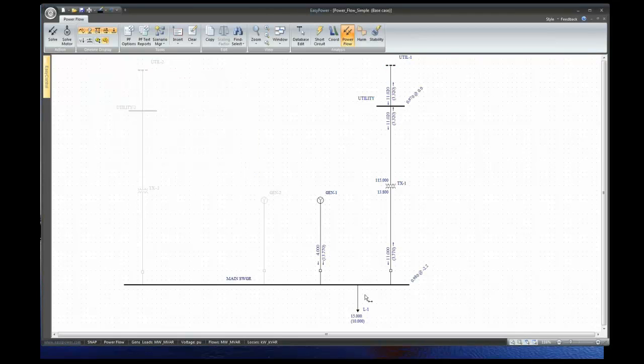So now what happens is this VAR requirement goes way up, right? Because I have 0.97 here, so I have even more voltage drop across the transformer. The only way I can maintain this voltage is to pump more VARs in from the generator. So now you can see I still have 11 megawatts coming in, but I have 3.77 megavars going back out into the system.